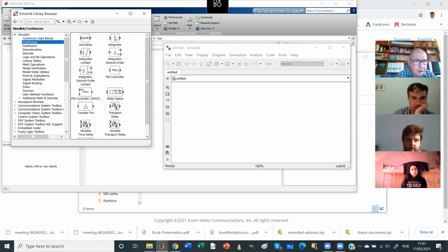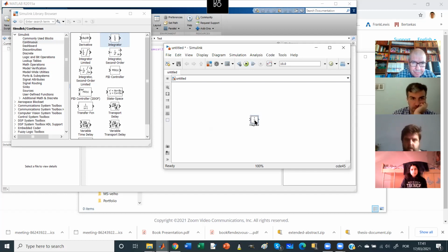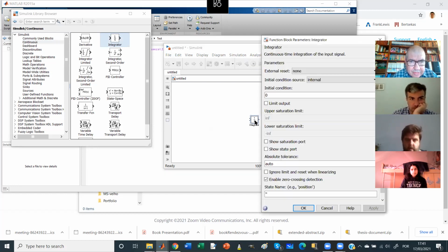The integrator is here. I click and drag it here. Now I will give some initial condition, say 5, whatever you want. For the moment, let's ignore everything else. So I do here OK or apply.